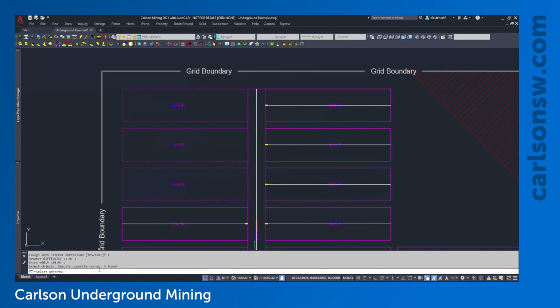Now when you're adding in additional panels, I've got to be careful not to reselect any of the panels that I already made. If I do that, it's going to duplicate the panels. It can just get a little confusing when you've got 2 panels on top of each other. So I'll be cautious about selecting them. Adds the panels back in, no problem.